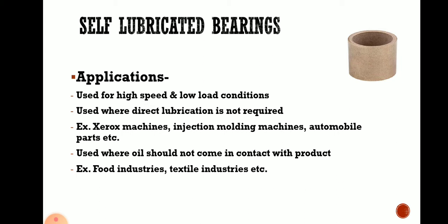So in those cases you cannot do the lubrication every time. There it must be self lubricated. So in these applications, generally the self lubricated bearings are used.